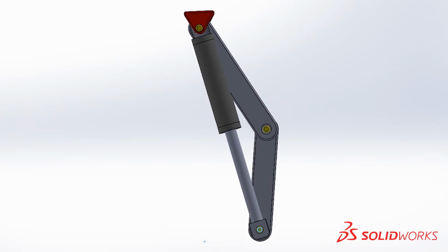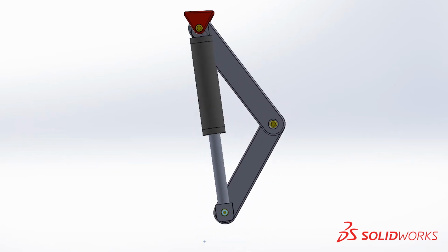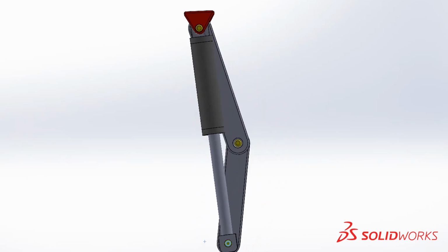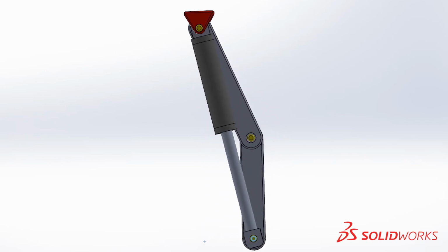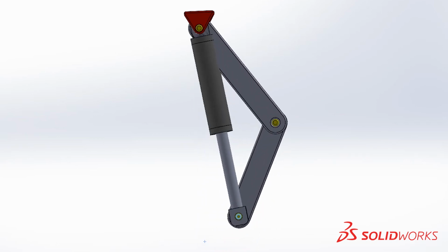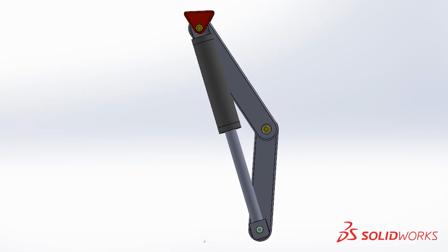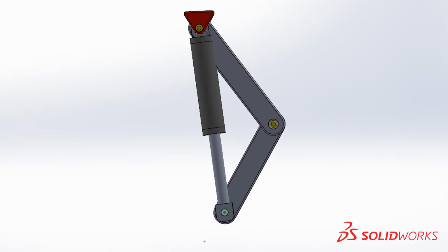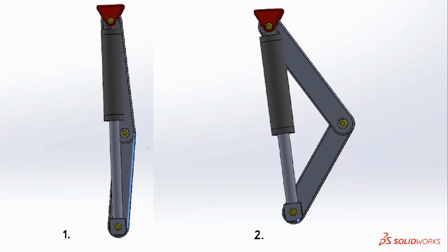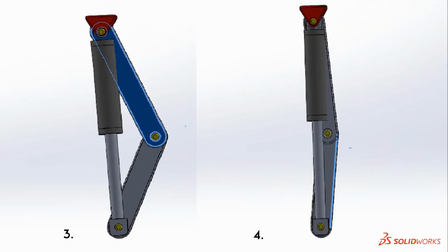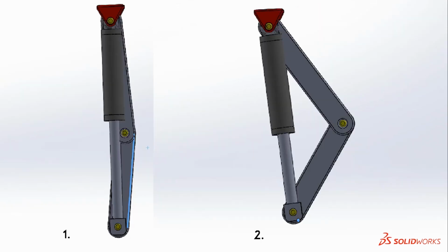The simulation was done on SolidWorks. Here, the thigh and the leg are considered as links, followed by a hydraulic, which is being used to provide damping, while a motor is being used to lift the leg, which is present exactly at the center of the thigh. Here, 1, 2, 3, 4 represent the subsequent movement of the link while a person takes a step while walking. You can note here that the hydraulic being used also helps as a support.